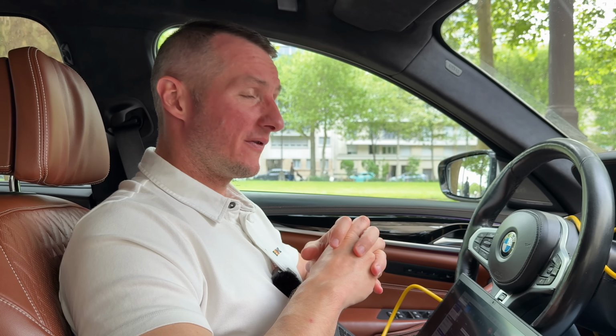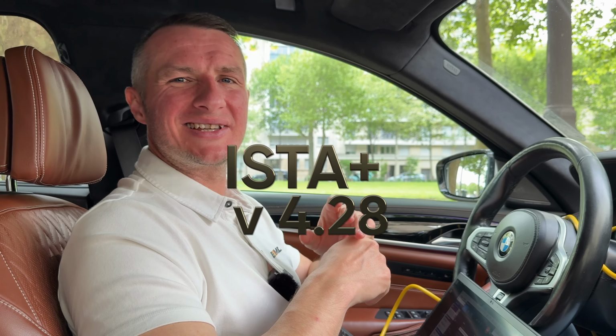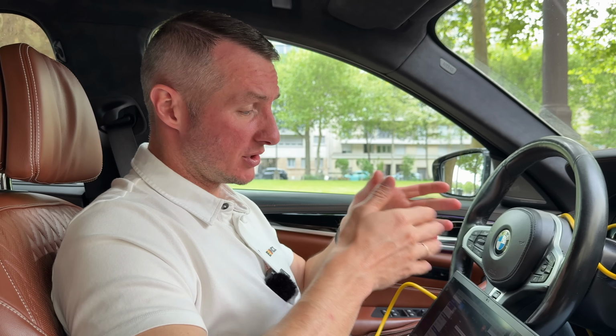It is super useful. For example, you are working at home, you are not connected to any vehicle, and you need to see some kind of wiring diagrams or whatever other information that ISTA could provide. It is super handy, but it's not present on all the versions of the ISTA. The last ISTA version I'm aware of where that tab was working was 4.28, but it's a bit outdated for the diagnostic purposes, but it's good to see different wiring diagrams.